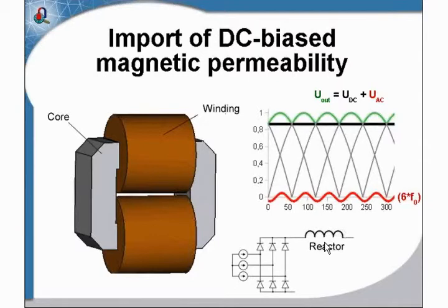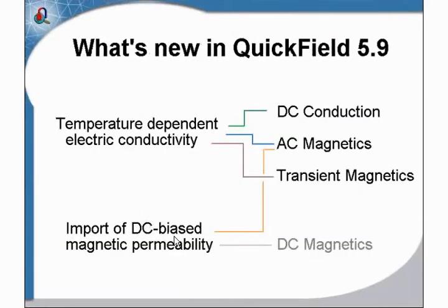Now, what the inductance value is, I cannot calculate it with DC, as it is not the DC current inductance that I need to know. I cannot calculate it with AC, as the reactor could be saturated by the DC current. What I do now, I calculate saturation level in DC, and then I import the magnetic state to AC magnetics problem.